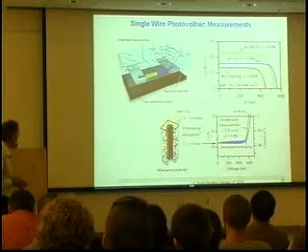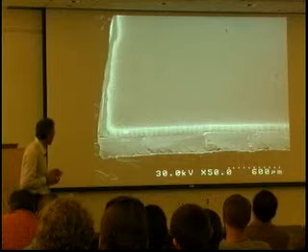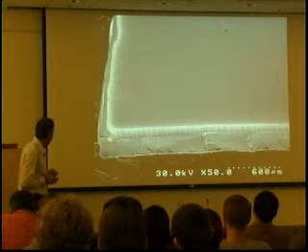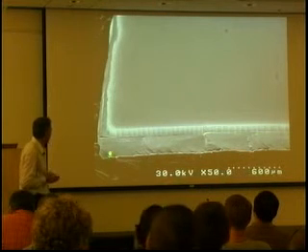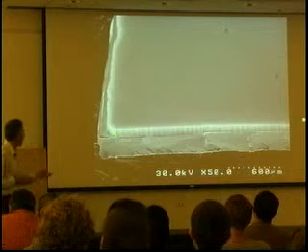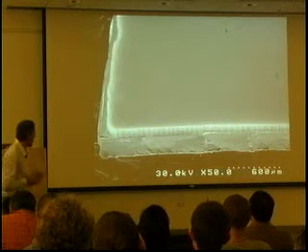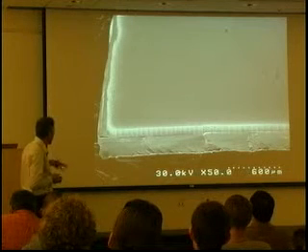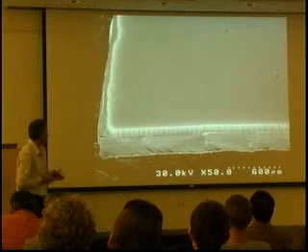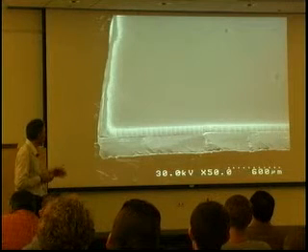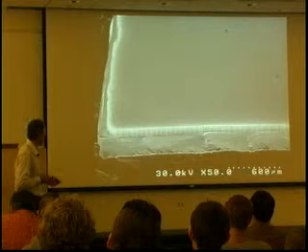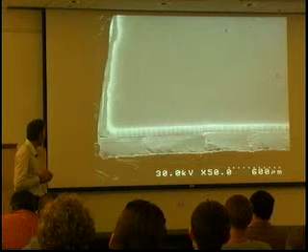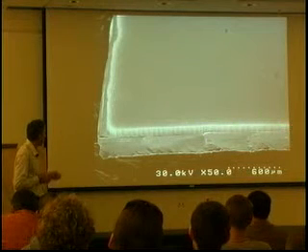Well, it turns out that we can peel these wires off. We embed them in a polymer, and we can peel them off and reuse this substrate. So essentially, this becomes a reusable template, and the wire array can be embedded in a polymer as a flexible sheet. We can make something that has the characteristics essentially of just a thin sheet of EVA or PDMS that has a bend radius of curvature of millimeters, and reuse the substrate many times.